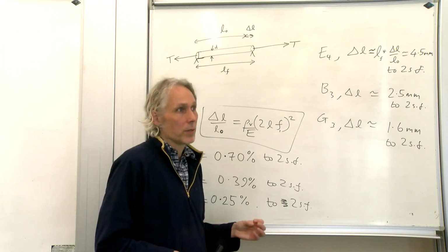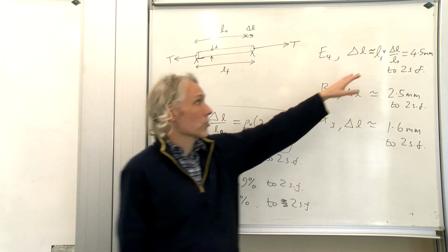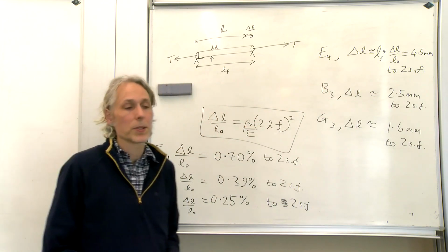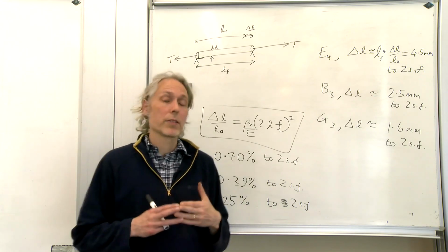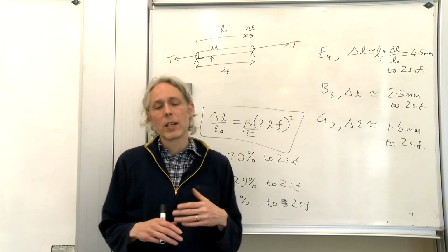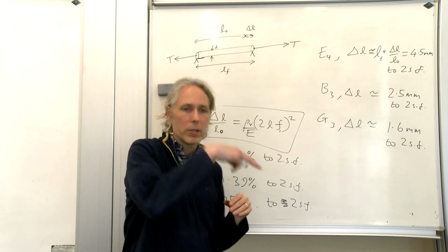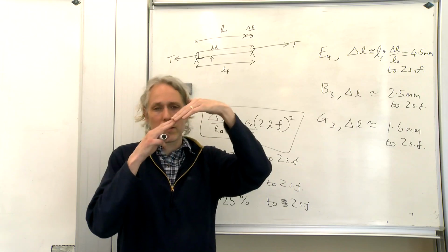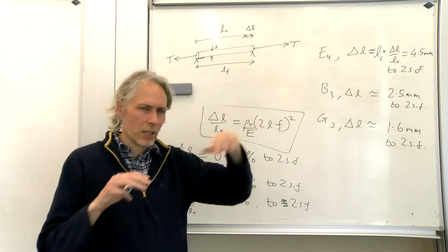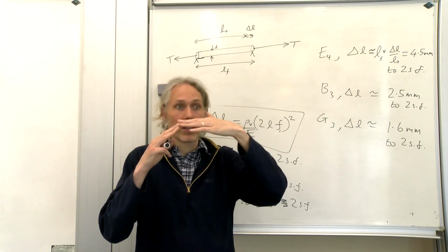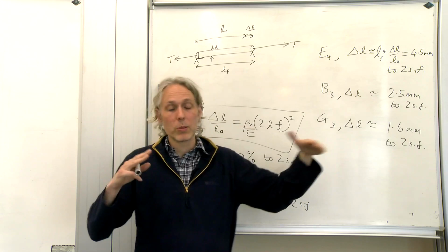So that can be especially bad for very thin strings where you need them to strain harden a bit as they're getting stretched quite close to the limits of what the material can take. And it can be quite bad for thick strings as well, especially if they're curving over the bridge initially instead of actually having a corner where they're going over the saddle. The string might bulge a little bit over the saddle, and it takes a while for the string to think, yeah, maybe I should be bending more at that point. And so initially you play the string and the string bends and sags and gets shorter and loses tension, and you tighten up the string again and it ends up being nice and stable eventually.